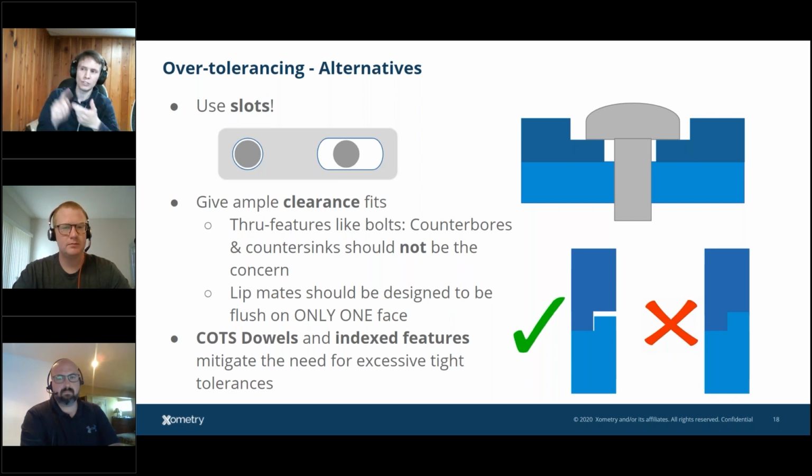So again, these are usually used when parts are mating or assembling with each other in some way, shape, or form. I made this little slide because at the same time, I like saving costs on my design. So anytime you're adding some of these tolerances like position or especially things like profile, surface, you may accidentally or intentionally dictate a measurement method that's going to add time and expense.